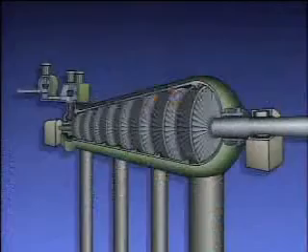Most modern turbines combine the use of impulse blades and reaction blades to make the most efficient use of the energy in steam. It is the designer's job to determine the proportions of each type of blade required in a turbine. Most large turbines are almost pure impulse in the first stage, almost pure reaction in the last stage, and a combination of the two in between. Now, you won't be designing turbines, but understanding what's going on inside will make you better equipped to operate them.